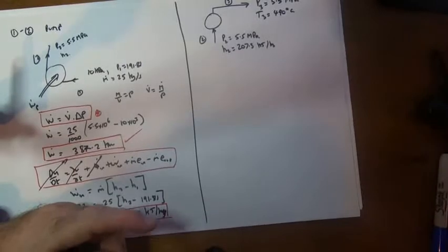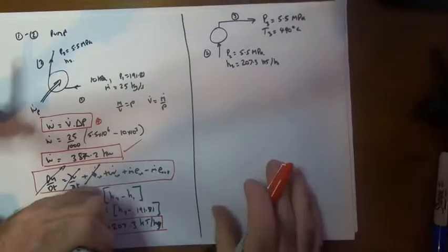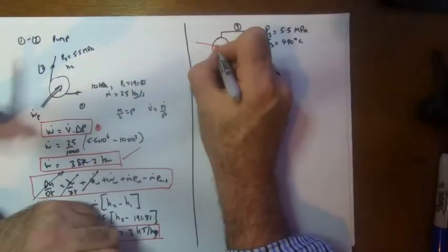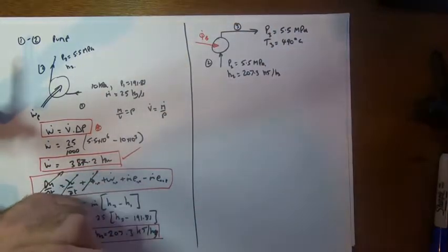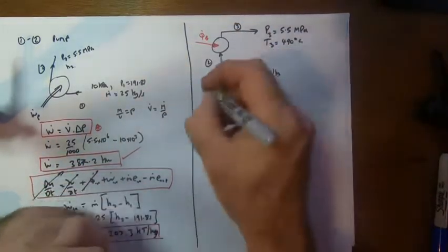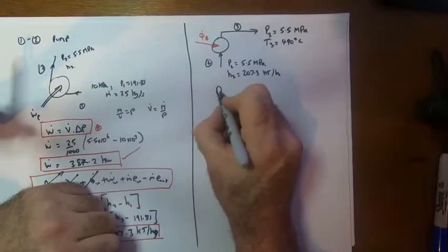So, energy transfers now. When you do your sketch, we show the energy transfers. So we have a Q coming in, the Q to the boiler. It's one of the unknowns we're trying to find. We can do our energy accounting equation for our boiler.